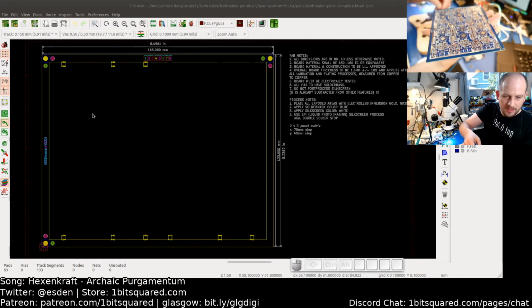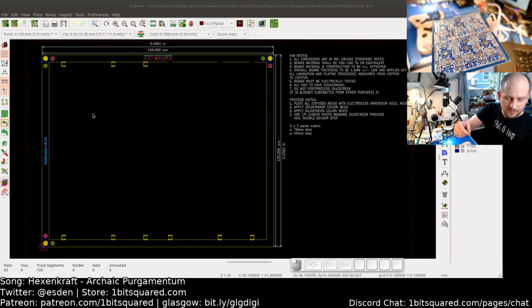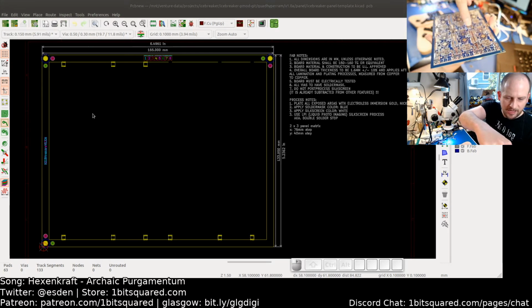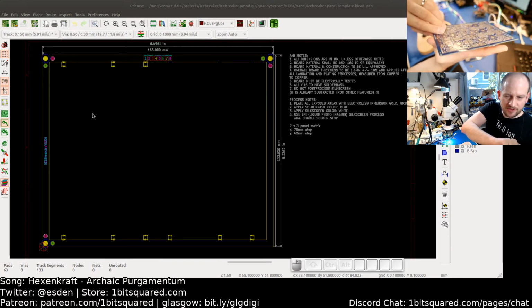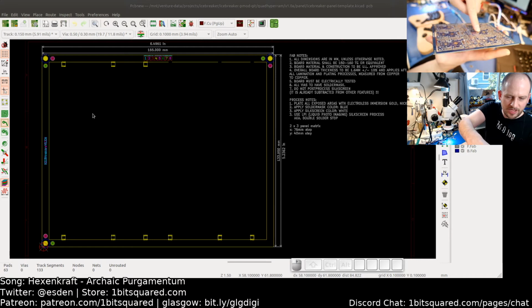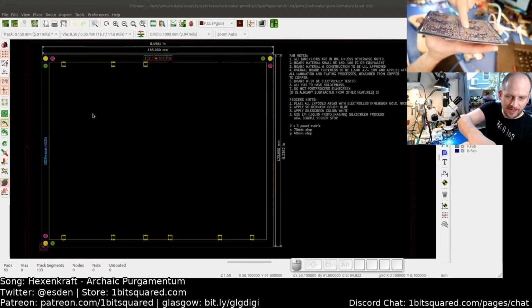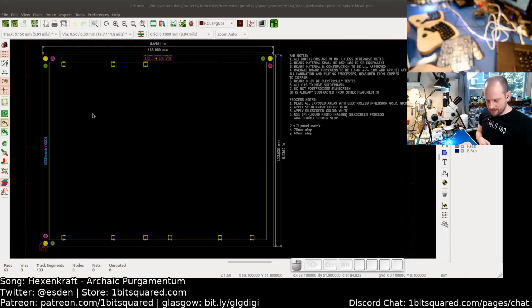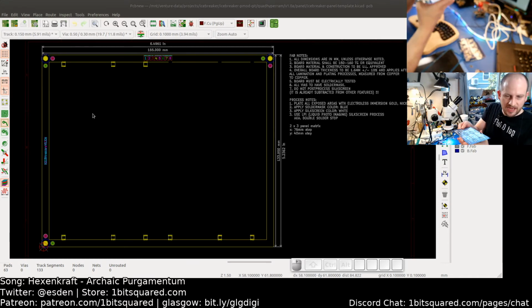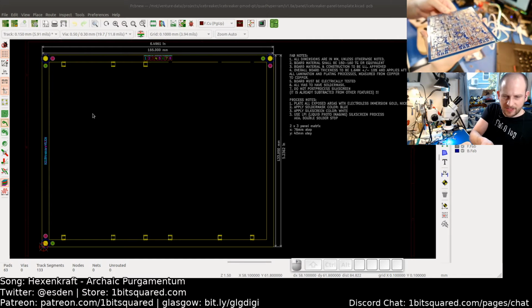And the board goes into the pick and place machine, and the pick and place machine will place parts on here. And this gets pretty good. It is still not flexing too much, which is nice. Even the bigger problem would be in the length. So this is more flexible in this direction than in this direction. It is much more rigid because it has those tabs. So that's how I put them together and how I decide which way it will go onto the rails in the pick and place machine.